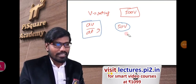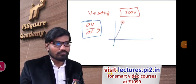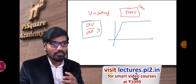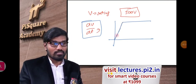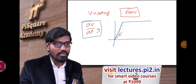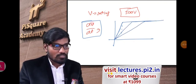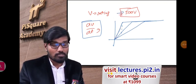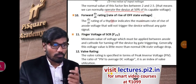What is this dV by dt? dV by dt says at what rate the voltage is changing. It doesn't talk about the absolute number, how much the voltage is. It talks about the rate of change of voltage. Is the 500 volt change happening in this fashion, or very slowly like this? So this talks about the rate of change of voltage, not the voltage magnitude. Be careful with that, that's the difference. You will understand this during turn-on methods.